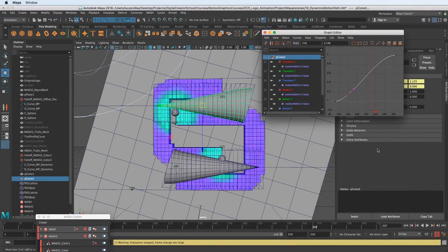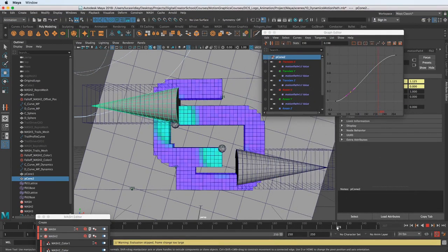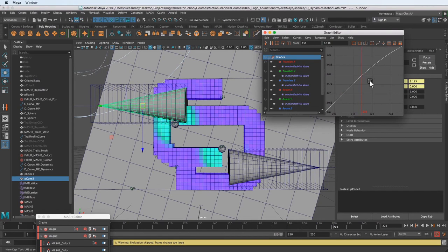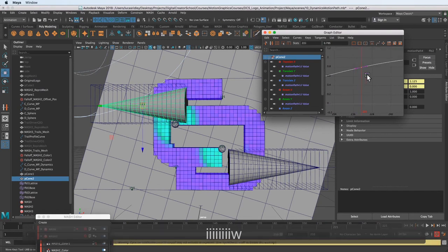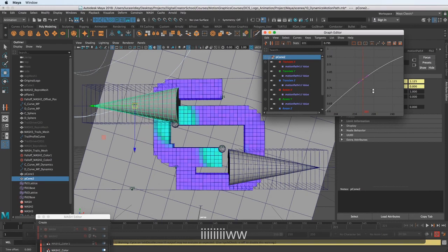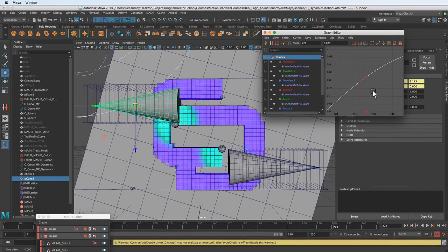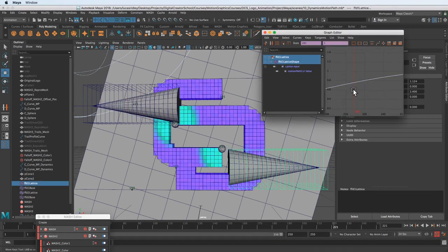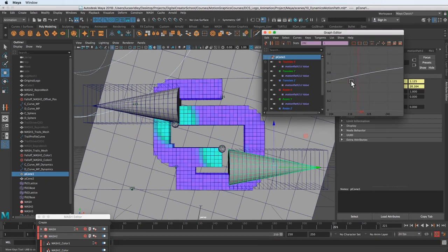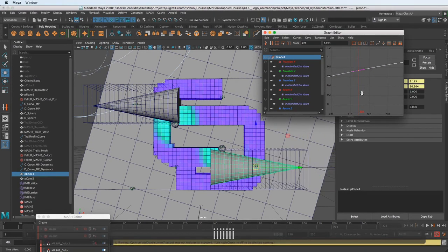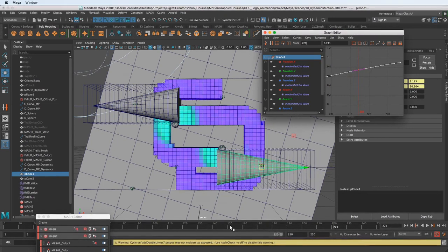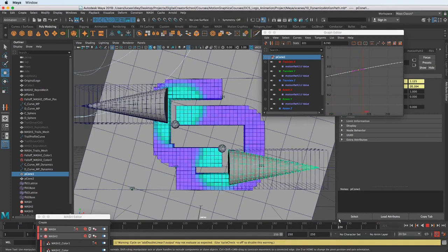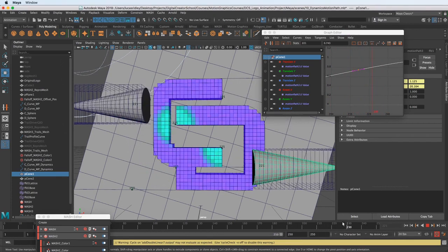Again, for the same reason, we need keyframes where we want it to definitely end, which is around where the spheres end. So let's set a keyframe here, because all of this is being timed based off of where the spheres are. That one was pretty close. This one's way off. So let's select the curve, hold down I, middle mouse click, and then bring it back. Cool. So now it should start at 150, and it should end when the spheres are done. The tail end of this thing should go through when the spheres are done.